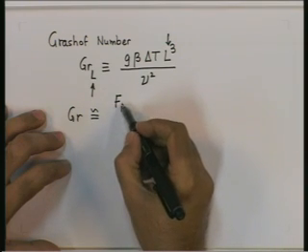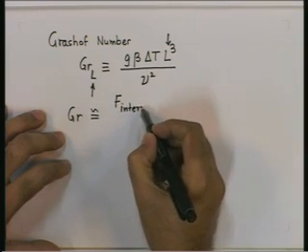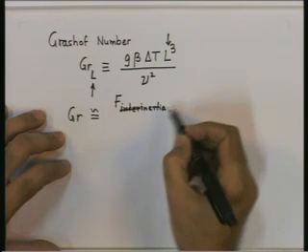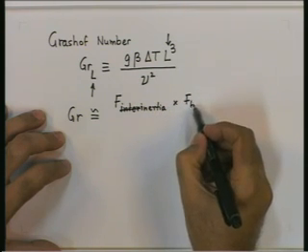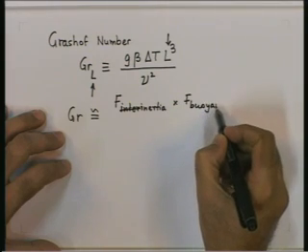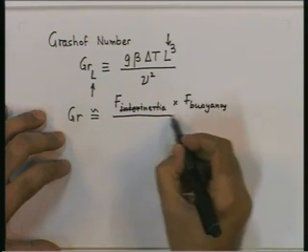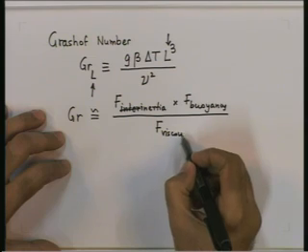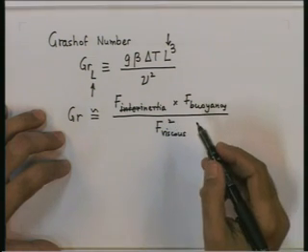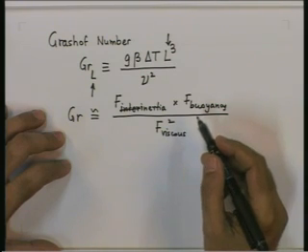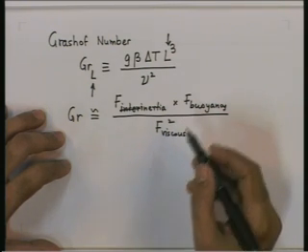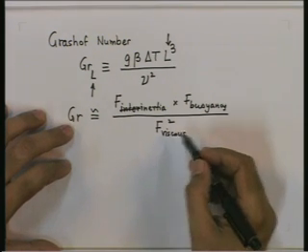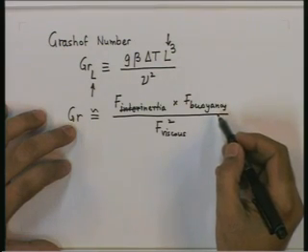are like this. You put inertia force multiply it by the buoyancy force and divide it by the square of the viscous force. This is the representation of the Grashof number, the significance of the Grashof number. If the viscous forces dominate, Grashof numbers would be small. If the buoyancy forces dominate, Grashof number will be large.